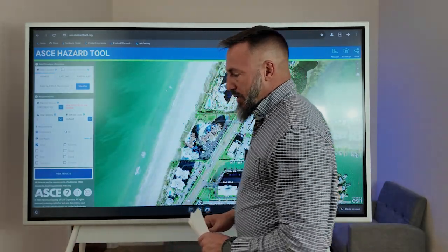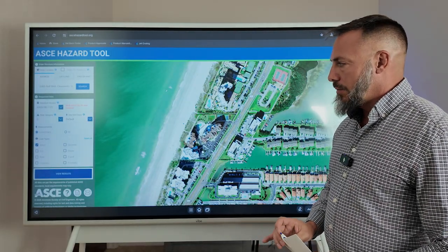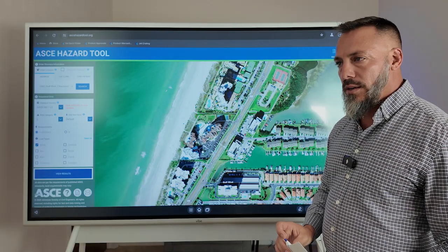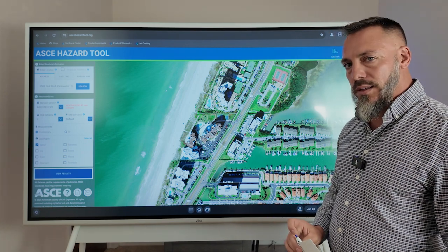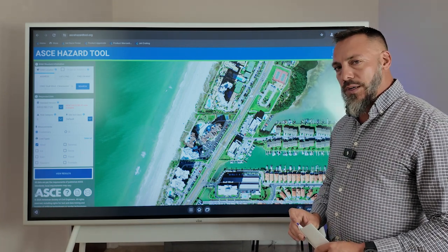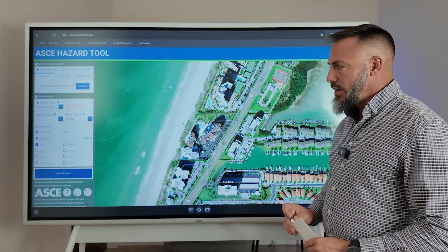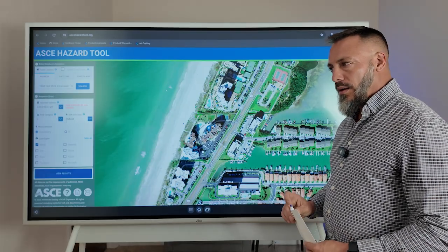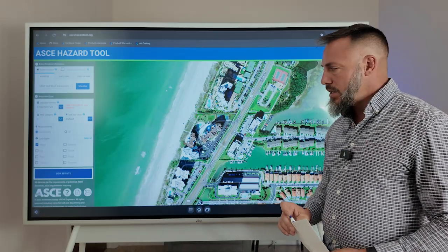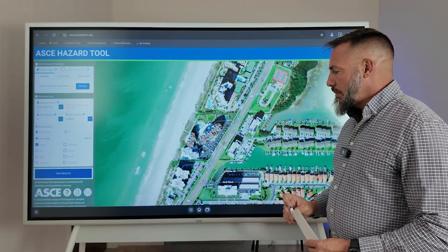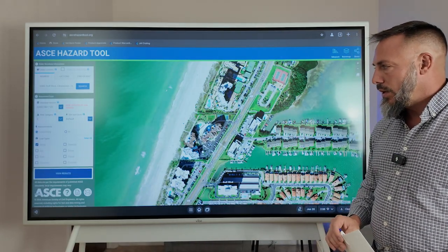The delineators between that: risk category 1 is any structure that doesn't house people, like barns or anything that's not occupied. Risk category 2 is the next step. It's most residences or anything that will house 300 people or less. Risk category 3 structures are anything that hold 300 people or more, so a condo, a hospital that doesn't have an emergency room, any large structure, a school that doesn't act as a shelter when a storm comes through.